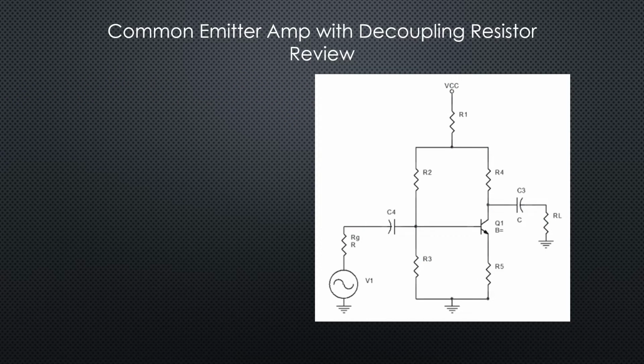Okay, now let's work on Z out. Let's go to maybe a lighter color. Z out is the impedance that the load sees. Again, these coupling caps are doing their jobs. We don't have the bypass cap up here, so we're going to have to factor in all that impedance. We're going to start as far away as we can. We've got Z out.